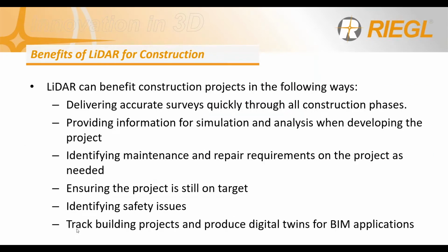So LiDAR can benefit construction projects clearly in a multitude of ways. You can deliver your accurate surveys quickly through every construction phase. You can provide information for simulation and analysis when developing your project. You can identify maintenance and repair requirements on the project as needed in real time, ensure that your project's staying on target, identify potential safety issues, and track your building projects and produce digital twins for BIM applications as you go. So this increases your productivity, reduces your survey costs and errors, and allows for real near-time information for quick decision-making.